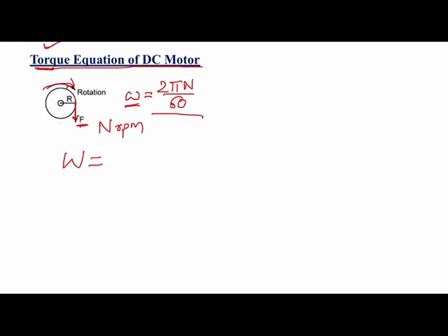So it is the circumferential force F applied on the wheel into the distance traveled in one revolution. Starting from a point, it covers the rotation and comes back to the same point, which is one complete revolution. So the distance traveled in one complete revolution is the circumference, which is 2 pi r. So this is the work done in one revolution.